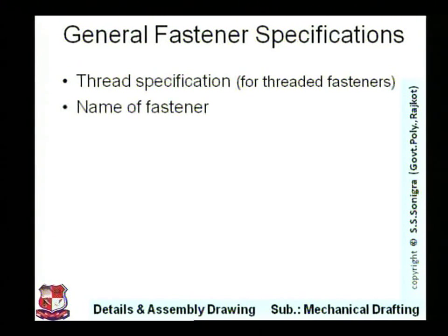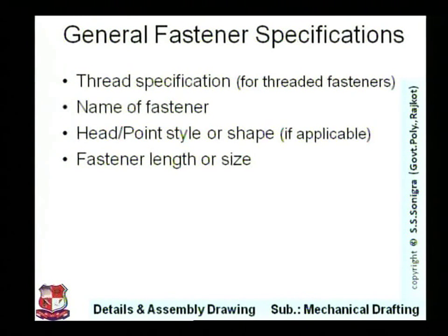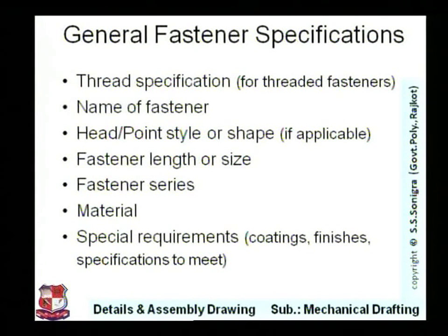Second is the name of the fastener, then head or point style or shape if applicable, then fastener length or size, then fastener series, material of the fastener, and special requirements, for example coating, finishes, specifications to meet, if any.